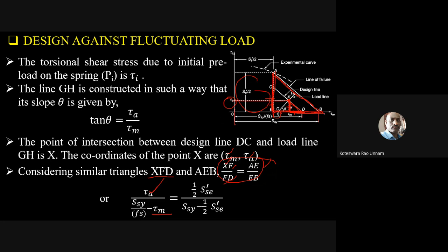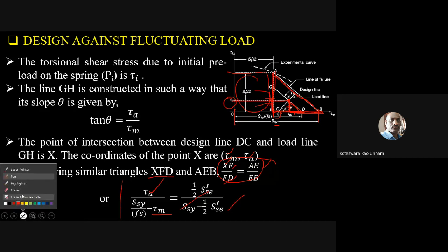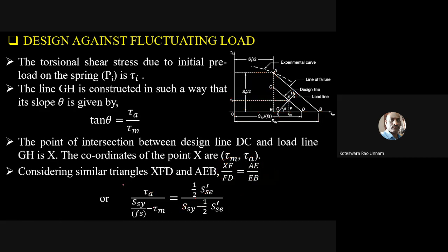So from here to here it is SSY. Then I have to subtract this one, which is nothing but again the same thing here, SC dash by 2. So finally I'll get the equation for the design of helical springs which are subjected to this fluctuating or pulsating loads. In this equation, if I know all these things, I can calculate the factor of safety.